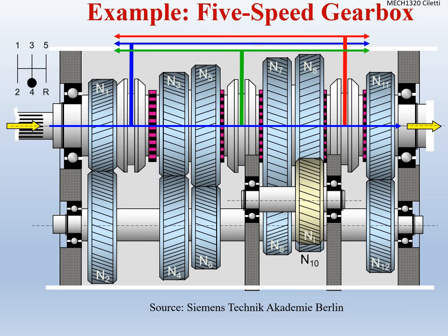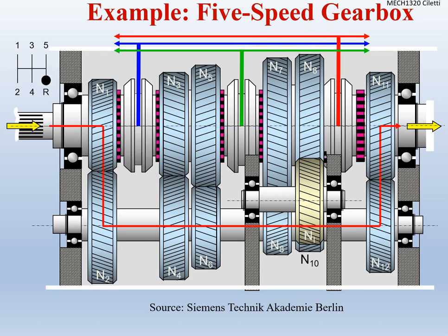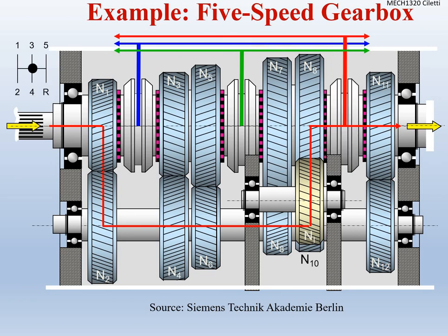Fourth gear, straight in line there, and we come over to fifth gear. Obviously we don't go straight from fifth to reverse, but we have our idler gear in there, and notice that it's reversing everything and reversing our direction so that we can back up our vehicle. So that's just a quick run through our gearbox and our transmission in our vehicle, back to neutral as we're driving through.